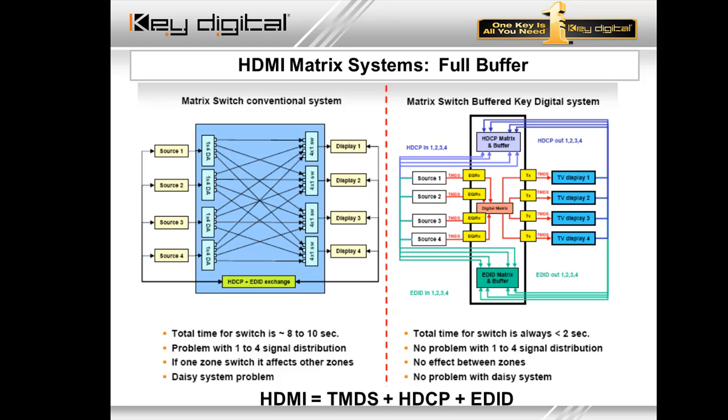Again, you saw earlier, how do we provide that EDID for the source, either from our default handshake library built into our product, or by copying from a display, adding it to our software, and then relaying it to the source. So it goes from here to here, from here to here to here, I should say, never from display to the source. Now what happens, that source is always authenticated just by one EDID handshake.